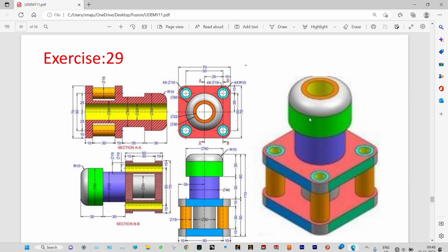So the pin is made. Now what we will do is, at the bottom surface we need to create this rectangular plate, and the plate will be having some specific holes at a specific distance away. The diameter of the holes will be actually 15 millimeter, and the rectangular plate is having length of 70 millimeter. Right, this is symmetric square plate of length and breadth equal to 70 millimeter, and at the corners of this plate some fillet is provided, and fillet radius is 10 millimeter.